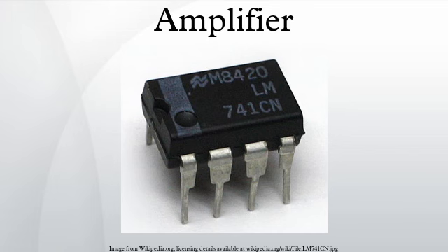In idealized form they are represented by each of the 4 types of dependent source used in linear analysis, as shown in the figure, namely, each type of amplifier in its ideal form has an ideal input and output resistance that is the same as that of the corresponding dependent source. In practice the ideal impedances are only approximated. For any particular circuit, a small signal analysis is often used to find the impedance actually achieved.